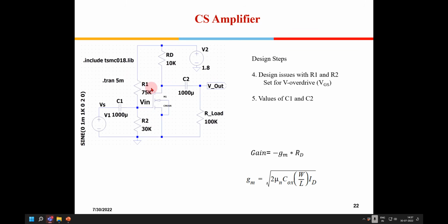The first problem is size, like you said. Since you brought one more aspect, there are three different problems. First is size, second is noise. When we do the noise modeling of resistors, larger resistance means larger noise. For RF applications, noise becomes a big issue. The third issue: I have a small signal here. This is a capacitance, this is a resistance. So this is like a what? It's a low pass filter or a high pass filter? High pass. High pass filter, right?